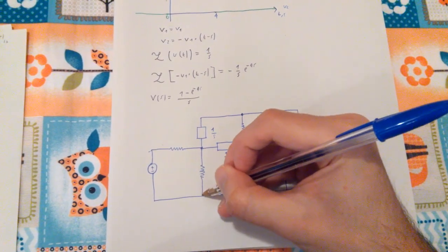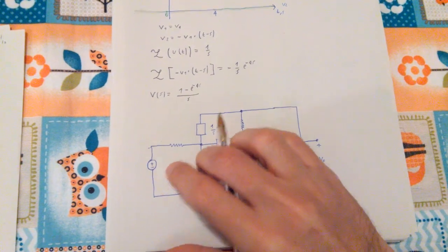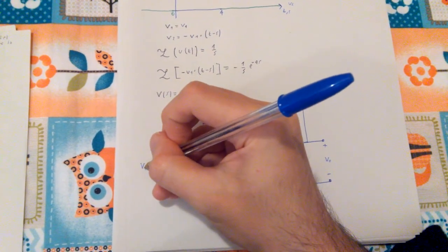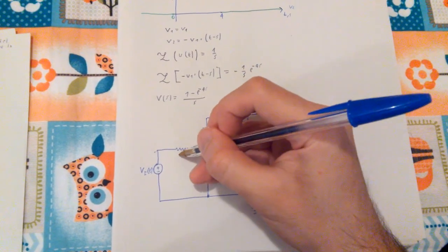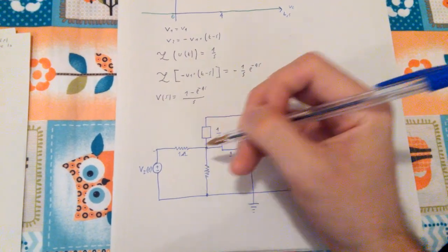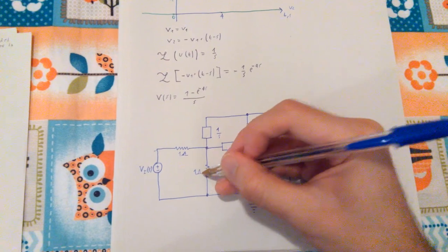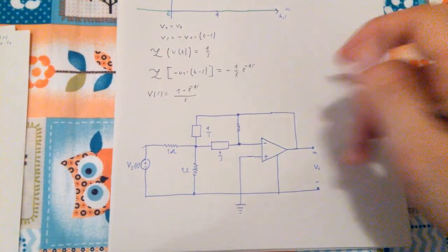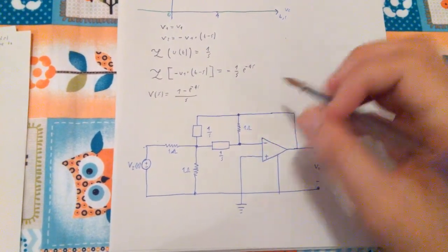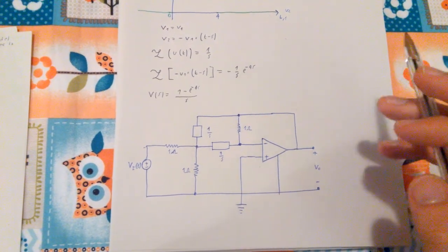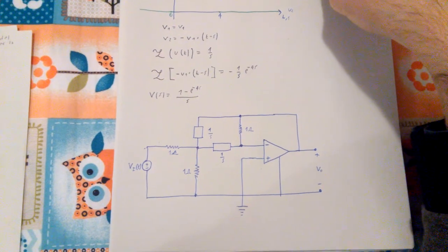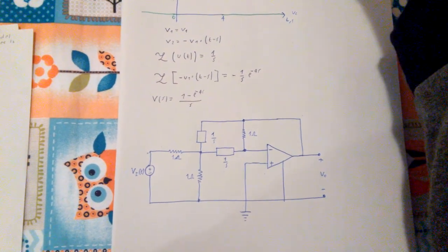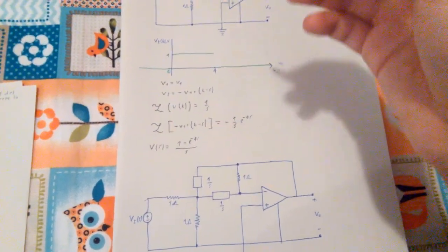And this one is a resistance. So we will still have, as I said, Vi of t, the time-dependent source, 1 ohm as this resistance, 1 ohm as this resistance, 1 ohm as this resistance. Those ones are 1 over S and 1 over S, minus plus. And this is actually the equivalent circuit of Laplace for this circuit.